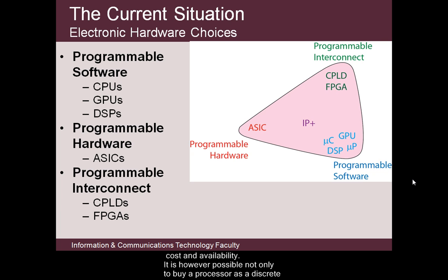CPLDs and FPGAs occupy the middle ground, as they comprise ready-built hardware that's customized by wiring the components together via reprogrammable interconnects. FPGAs are popular, particularly for prototyping, as a way to produce complex application designs at lower cost than ASICs, using VHDL synthesis tools. But it may still be a problem to match the hardware capacities available precisely to the needs of an application without wastage.